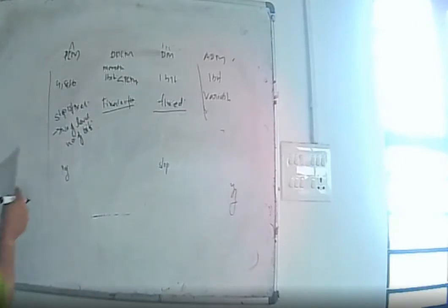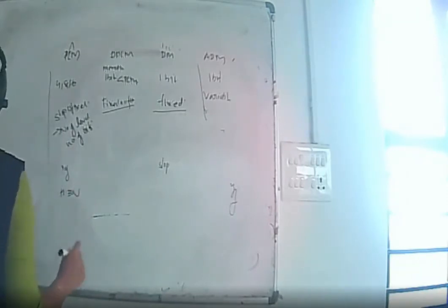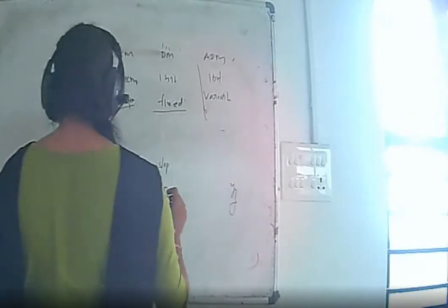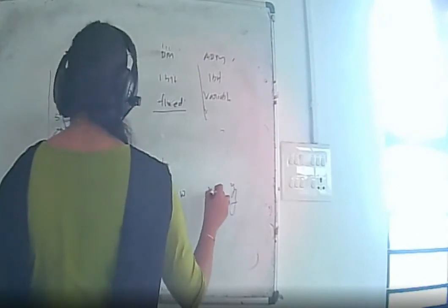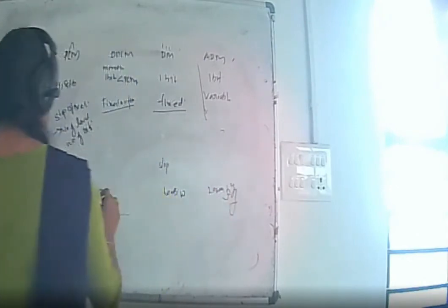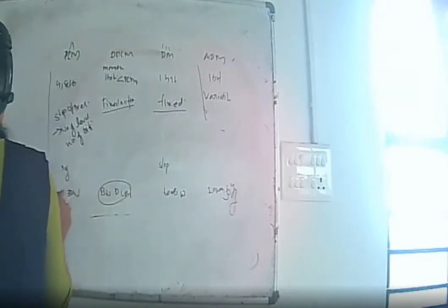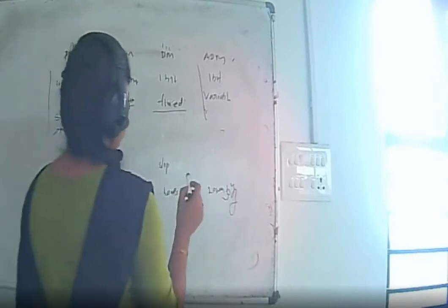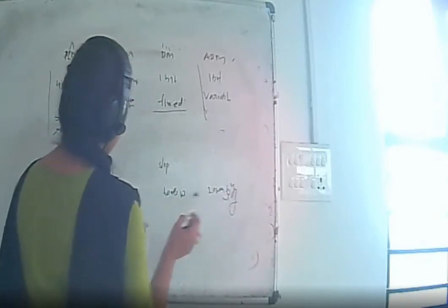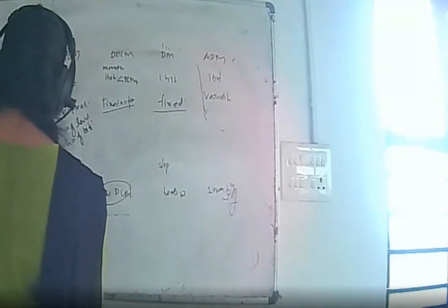In the case of transmission bandwidth, PCM has high transmission bandwidth, and DM has the lowest transmission bandwidth, and ADM also has lower bandwidth. Comparing bandwidth, PCM has high bandwidth and the lowest bandwidth is obtained in delta modulation and ADM. And in DPCM the bandwidth is less than PCM but not less than delta modulation and ADM.